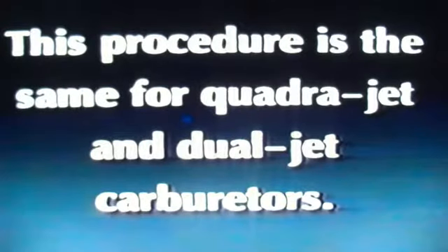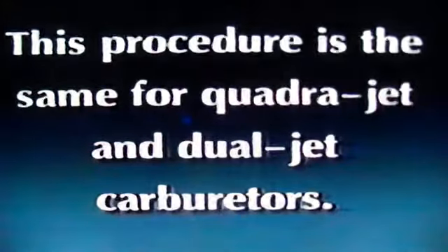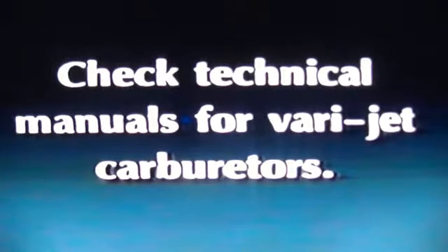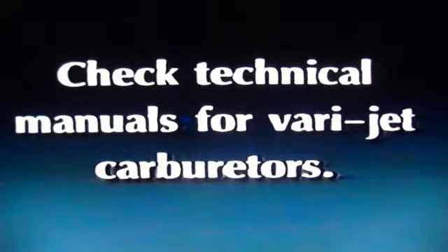We should note that the procedure you have seen here on a quadrajet carb is exactly the same for a dual jet carb. As for vari-jet carbs, the recalibrating procedure is a bit different, but not nearly as complicated because the vari-jet itself is not as sophisticated. By now, you can see clearly that this diagnostic procedure takes a lot of time and effort. But we feel it's well worth the trouble because it allows you to pinpoint and repair drivability problems that the trouble codes failed to detect.